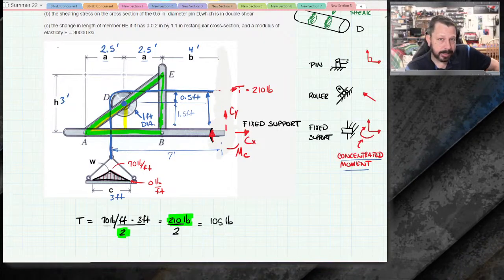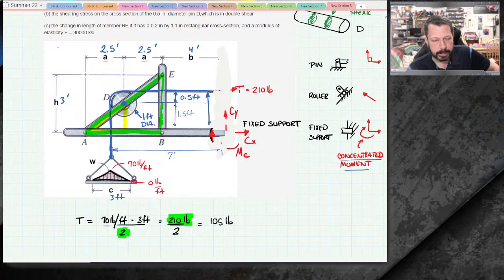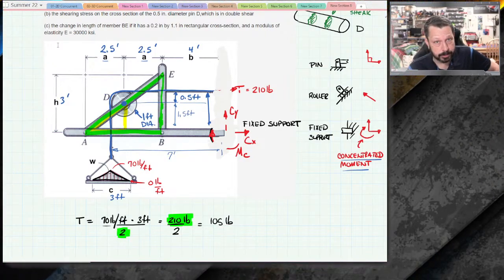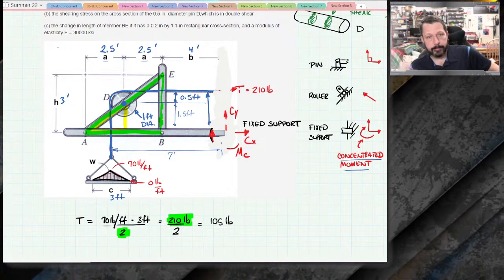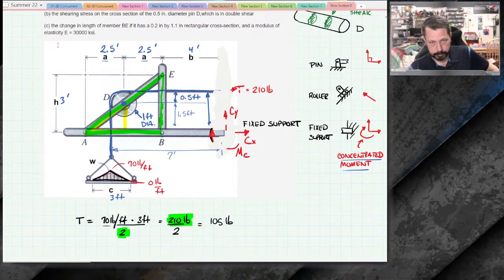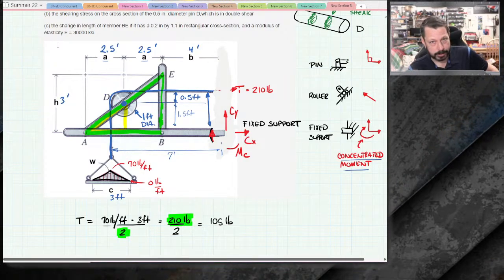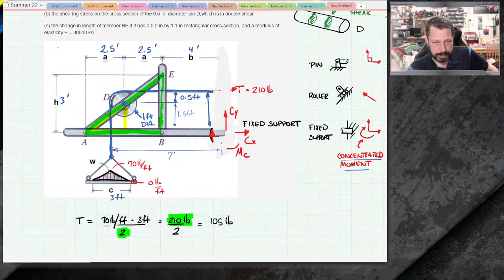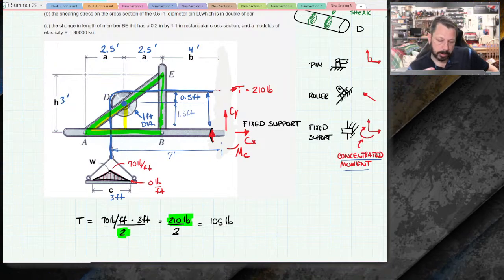The cable is technically a two force member, but it's different. It's not a rigid member like these others. So technically it would be two force also though. So we're looking for any of these pieces that follow the truss rules. They have only two pins, no external force applied to the body of the member, only forces are at the pins. So ABC has two pins and the fixed support, so it's definitely not a two force member.